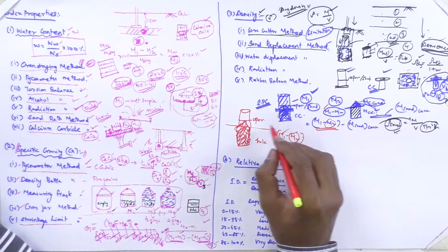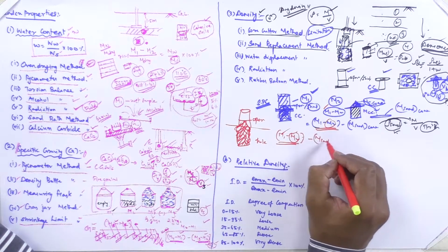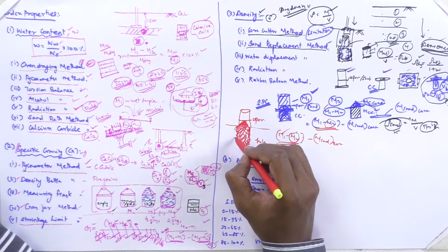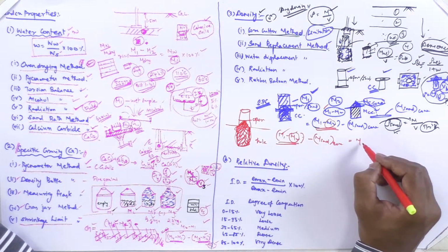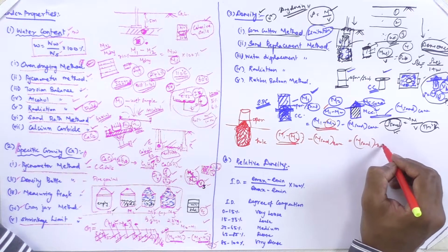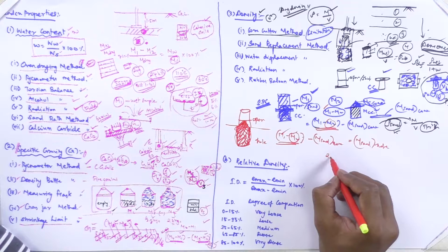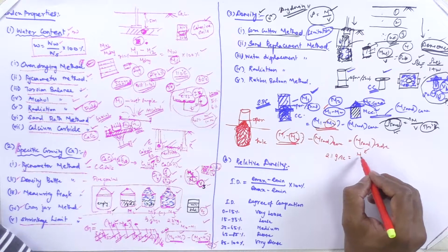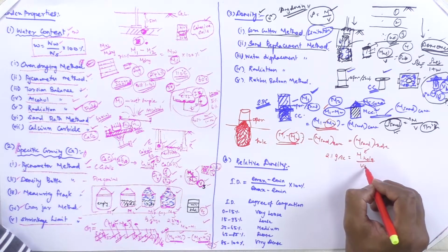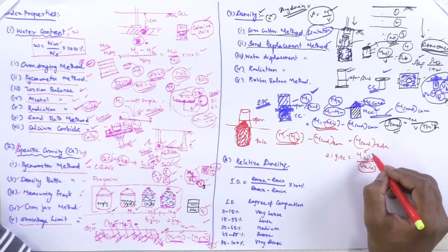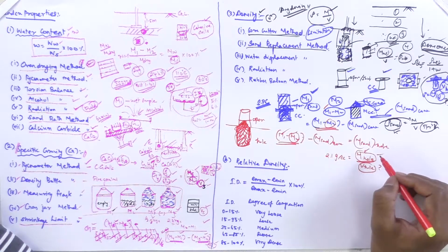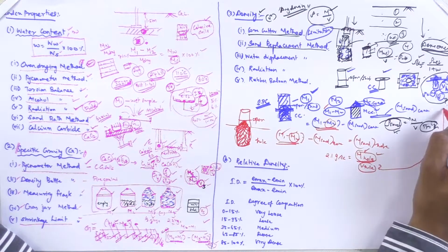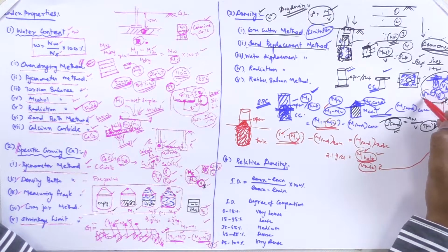So now, minus this mass of sand at cone, so minusing this, you will be getting the mass of sand occupied in this hole. So finally, you will be getting the mass of sand at hole. Now as you know the density, say the value is 2.1 gram per cc. So substituting the density, the mass at hole divided by the volume of hole, the unknown. So this is known at the end of the weighing balance results. So the volume of hole can be found out, and this is going to be substituted in this volume of hole. You will be getting the final answer as a density.